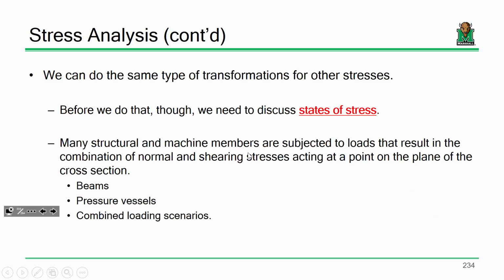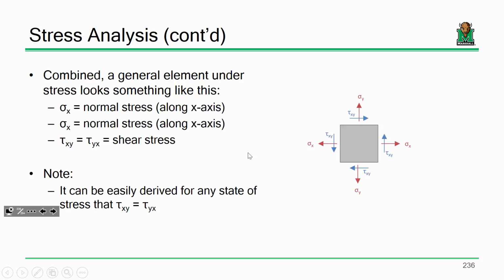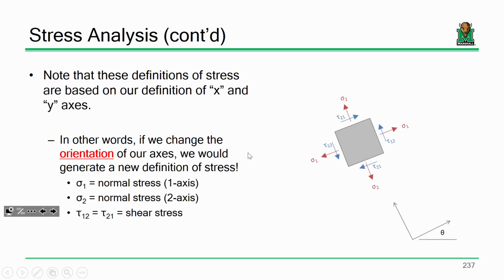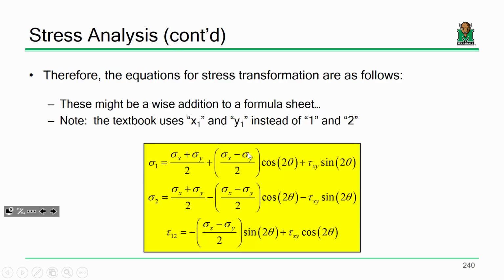And if I do the same thing for all the other potential stresses, the idea is that if I have a stress state that is defined with respect to just a random coordinate system, and I want a stress state with respect to another coordinate system, then summing everything up and doing all the algebra and keeping everything tidy, I get this. So this is sort of a nutshell: here it is, that will transform stress state 1 into stress state 2 depending upon a change of orientation.